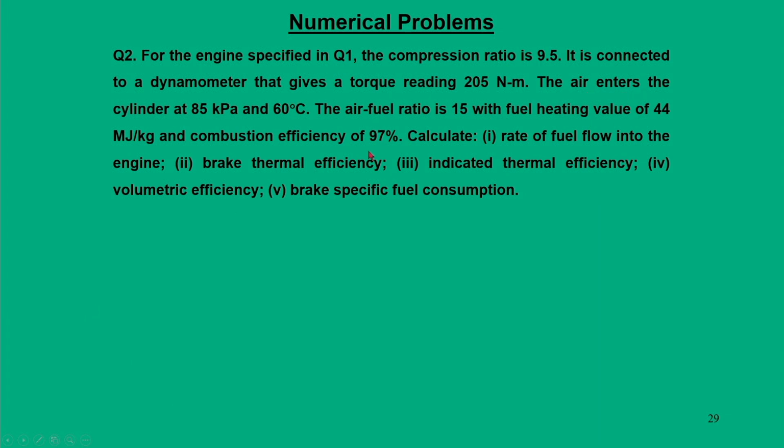Then once you have brake thermal efficiency, we can calculate indicated thermal efficiency, eta T I, as eta T B, the BTE, divided by mechanical efficiency. So, this is 0.3 by 0.85. So, this turns out to be 35%.